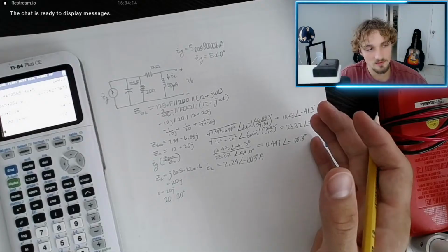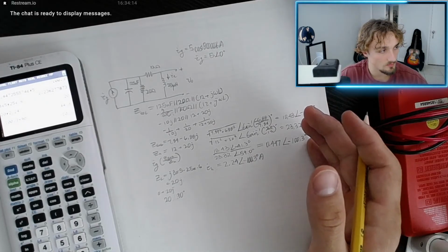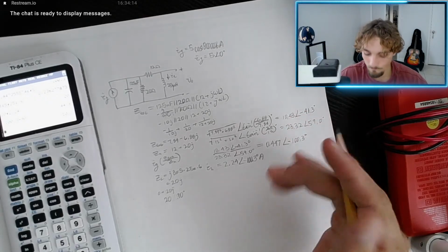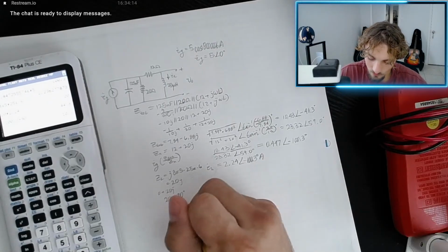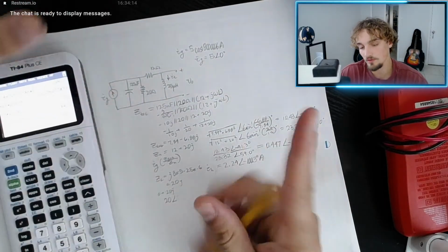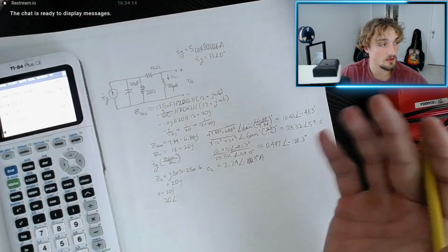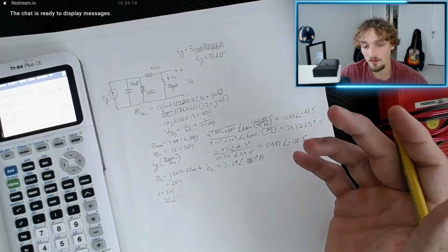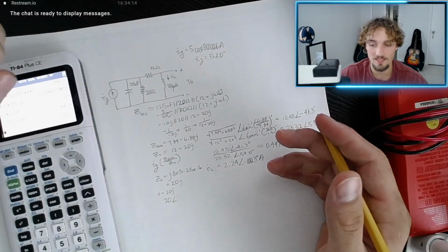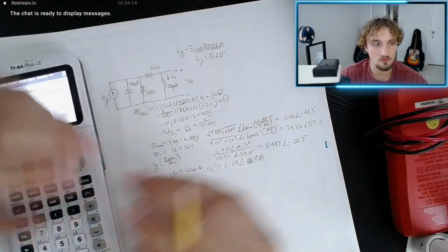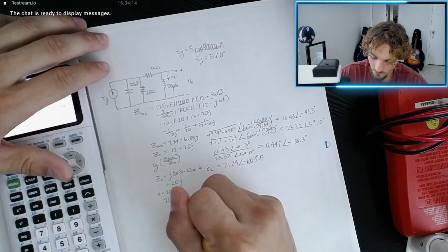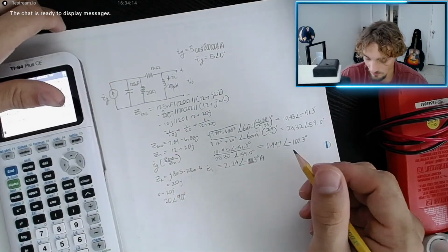It initially acts as an open circuit and over a long time begins to look like a short circuit. So the current initially lags, but we still consider it to be a positive 90-degree phase shift, right? Because if we were to model it in the complex plane graphically, it would point upward, right? The inductor impedance would point upward, and the capacitor impedance would point downwards and be negative. There it is. All right, so 90 degrees.